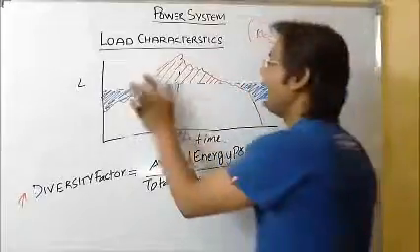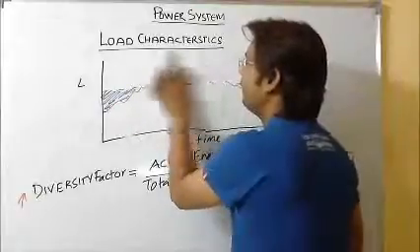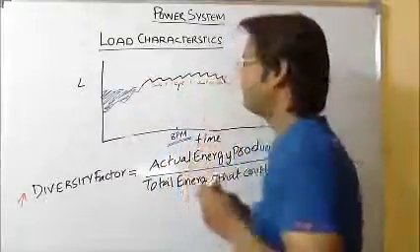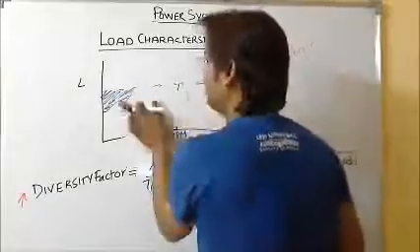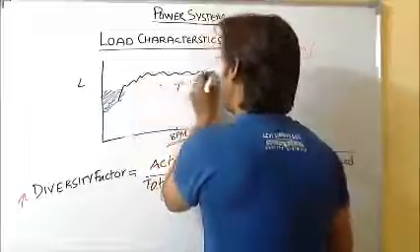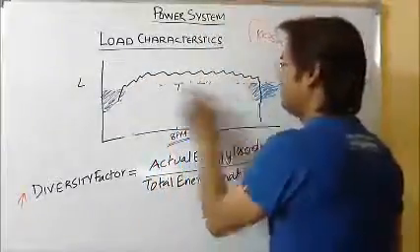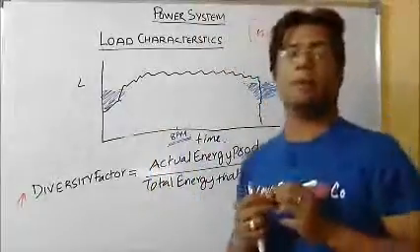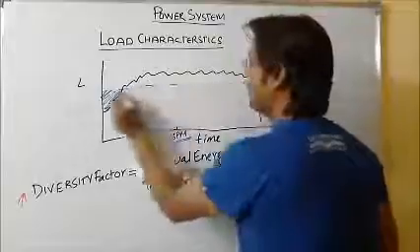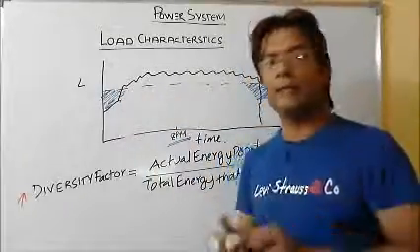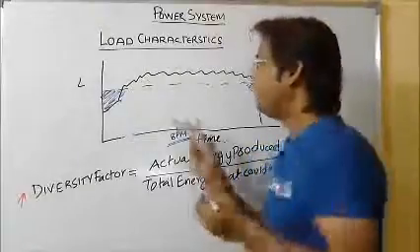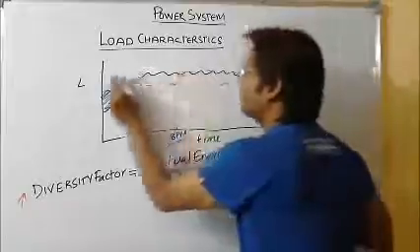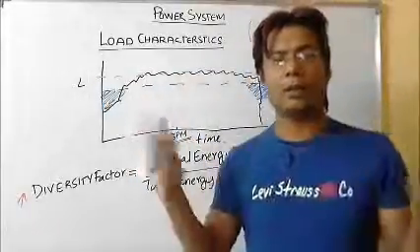If I do one thing, rather than having this much of a peak, if I am able to have somewhat like this, or I can have a graph somewhat like this, which is also equivalent to 100 square centimeter, which we have spoken about, and this was my installed capacity at that time. So at that moment, rather than everything going on at 8 p.m., everything at maximum demand at 8 p.m., I have a maximum demand of almost this much over a stretch of time.